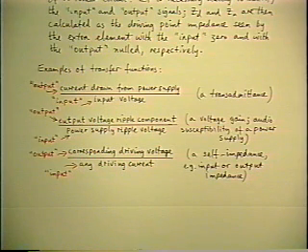It's going to have some rectified ripple on it, probably off the line, maybe 120 hertz or so, may even be a volt or two. And you have another specification on your amplifier that says that power supply ripple in the amplifier output has to be less than some specified value.